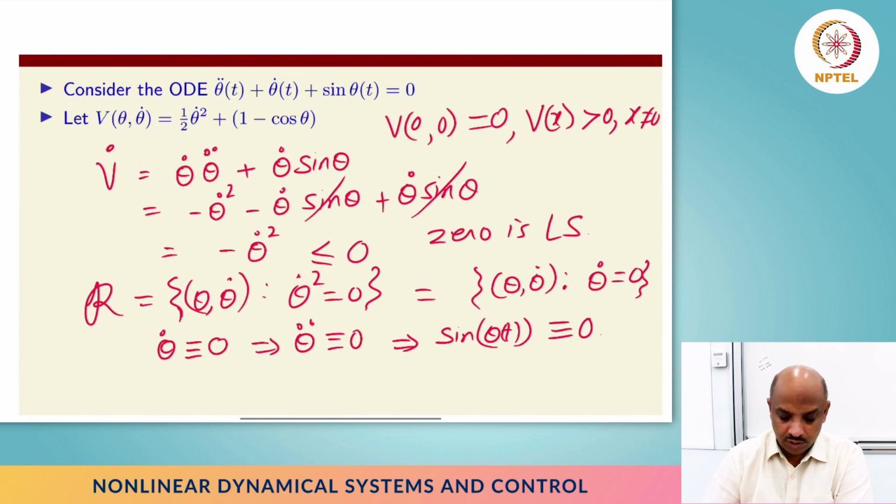So all the equilibrium points could be your answer, right? But of course, in this particular case, we showed positive definiteness only close to the 0 equilibrium point, so we can only conclude Lyapunov stability.